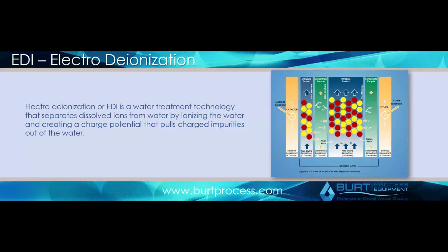When you get into very high-end water qualities, you also generally combine the two of them. So very often you will end up using an EDI in combination with a DI to achieve that 18 megaohm water that you're trying to achieve, either as part of an ASTM Type 1 or as part of an electronics grade system at that point.